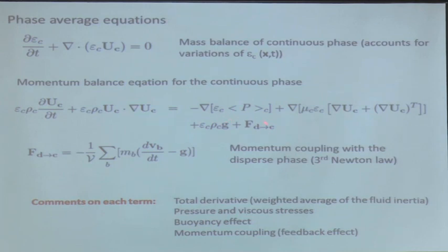And you know that because when you do the force balance, you know exactly what is the force acting on that particle due to the fluid, so you can take the opposite and inject that into the Navier-Stokes equations. And then that will modify, again, the equations, and then that will modify the response of the flow and its dynamics. Okay? So this is the way you can handle the effect of particles on the fluid through the equations.